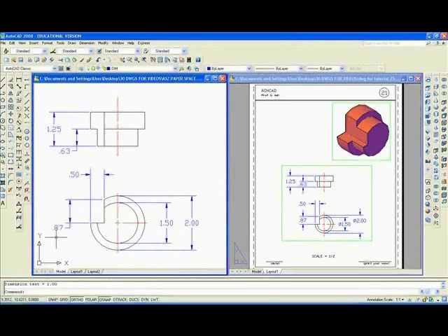And remember that if you want to change these, I'm sure there's other ways of doing it, but I haven't looked it up yet. In other words, I can simply take OSNAP and Ortho off, click on the dimension, then drag it to wherever I want to put it, like that. Same with this one. Hit escape.